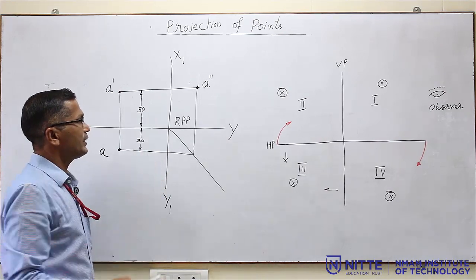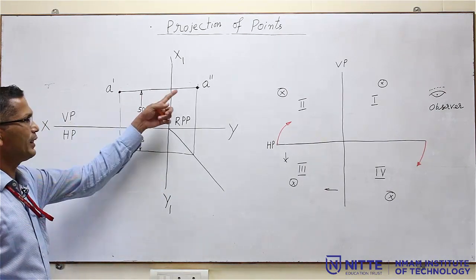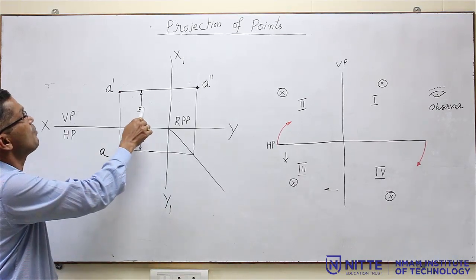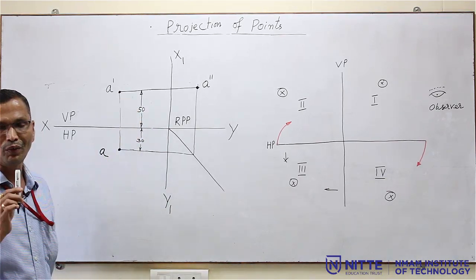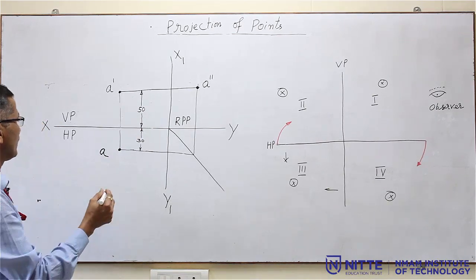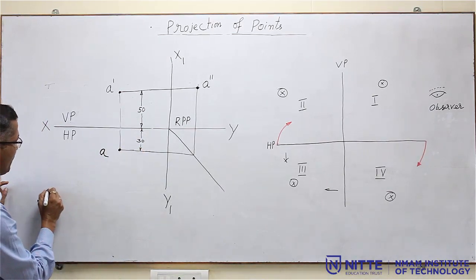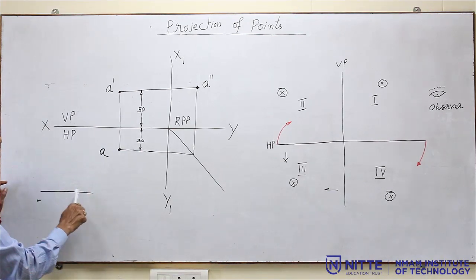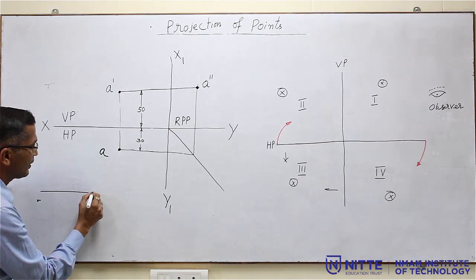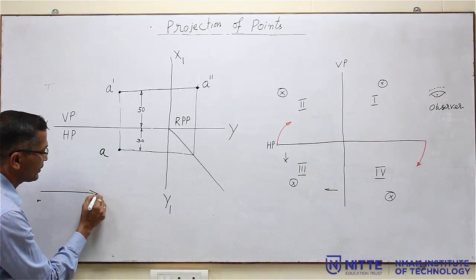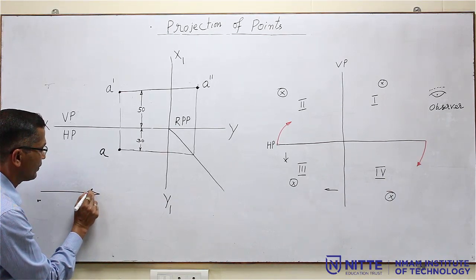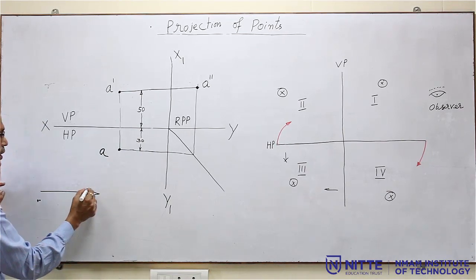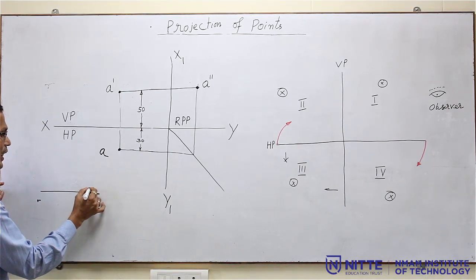Now, while solving this, because this is a very simple drawing, the weightages will be given for the dimensions also, how the dimension lines you are going to draw. Now, the arrowheads, what we are going to draw here, is also very important. So, draw a light line, then at the end of this the arrowhead like this.